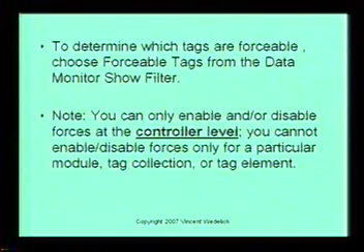And if you recall, when we were in the tag monitor or the monitor screen, we were able to sort on forcible items. Once we sorted on the forcible items, we all saw that that was only in the controller tag level when we had actually added the I/O module.